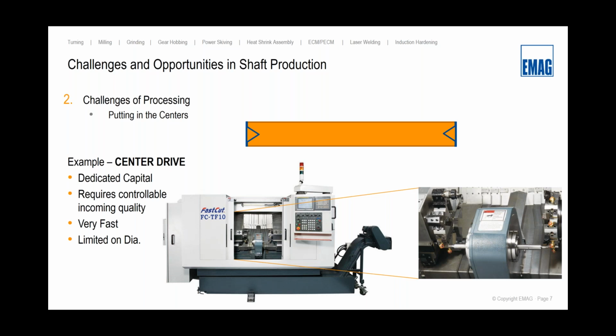I can thread the external features. I can drill through the center. I can use live tools on the turret to maybe mill some features. But the big benefit is you're doing those things simultaneously. The other big benefit is quality. In this case, you're clamping on the component and you're turning this thing at a high RPM, and that gives you a really nice quality benefit.